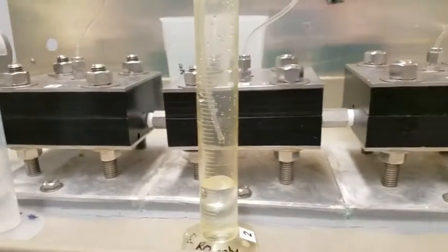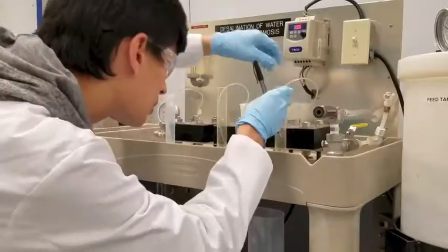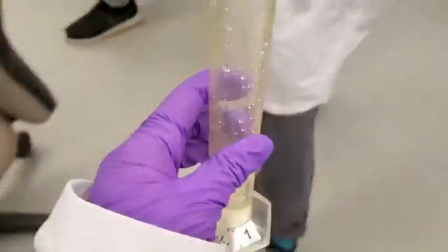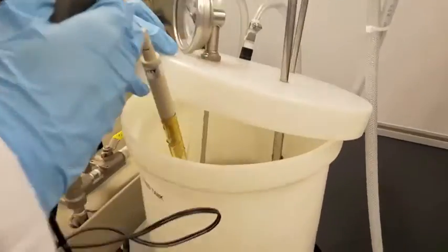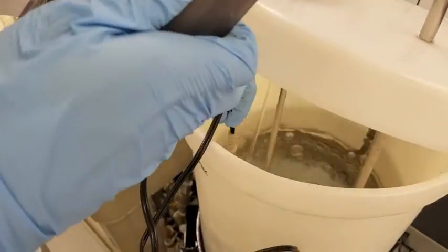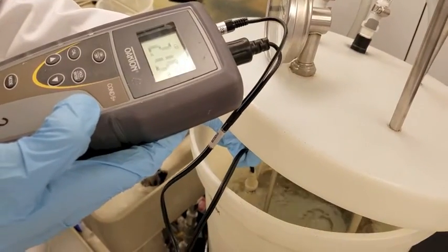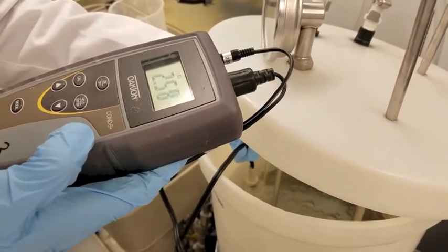Collect the desired volume of the outlet permeate from each cell and record the collection time. Weigh the graduated cylinders and use the probe, making sure the 2 metal bands are submerged in solution, to record the conductivity of all 3 cylinders. Then dump the water back into the feed tank. Remember to periodically take conductivity and temperature measurements of the feed tank as well. Repeat these steps at varying pressures, flow rates, and membrane types for the system.